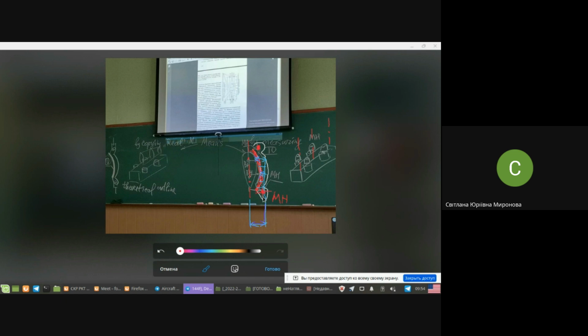It's a trick which substitutes one base. Originally it was this base, but now we substituted it with this base. Now, of course, we broke the principle of locating due to this, and as a result, we have less accuracy of this measuring than if we measure from the axis immediately.